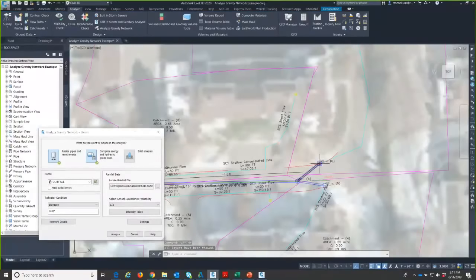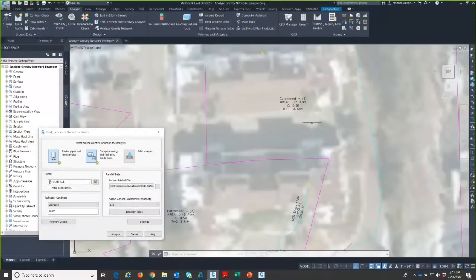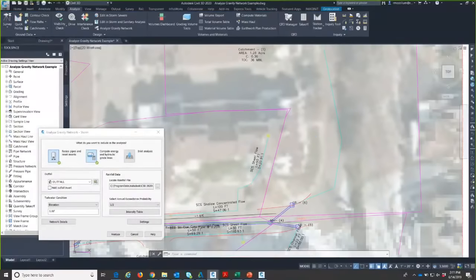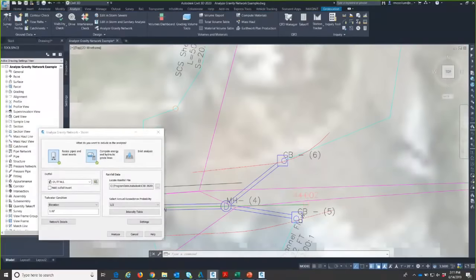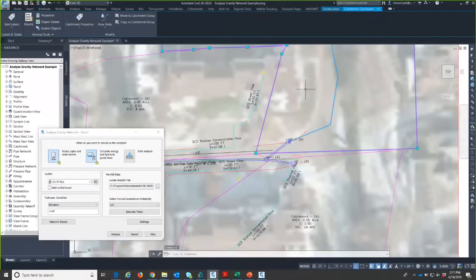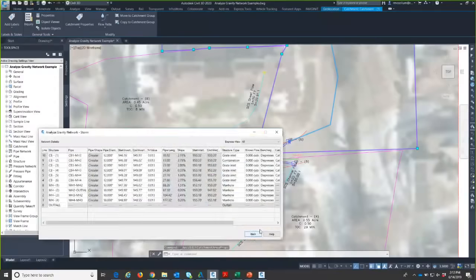So each one of these catch basins has a catchment object associated with it. So right here, catchment 1, with a specific C factor and area and calculated time of concentration, is flowing to catch basin C. I could make sure that those are all connected by, say, if I clicked on the catchment, if you ever use catchment objects, I could click right here and assign a new one by clicking this ellipsis button and then selecting my catch basin, or I can also use my new modeless dialog box